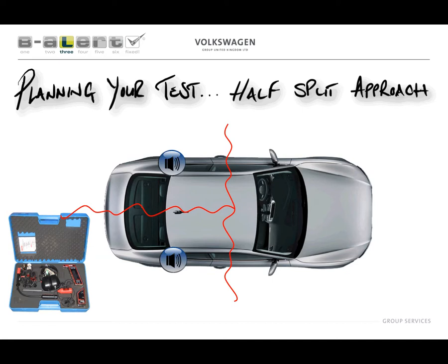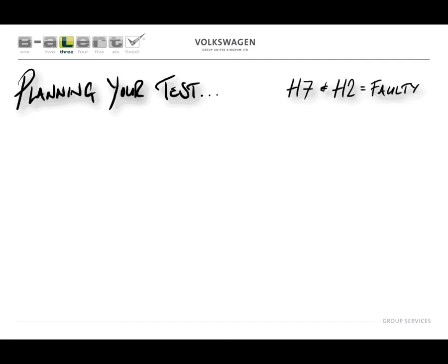So repeating the process a 3rd time will tell us again in a smaller area where the fault is coming from. Now do you see, when I carry this out 3 times, I'm always going to narrow down the fault to 1/8 of the circuit or the vehicle. What I could do now is go on to place one sensor on the body and one on the suspension, and it will narrow it down even further still. It's very, very useful. Now let me show you how to do this on an electrical fault.